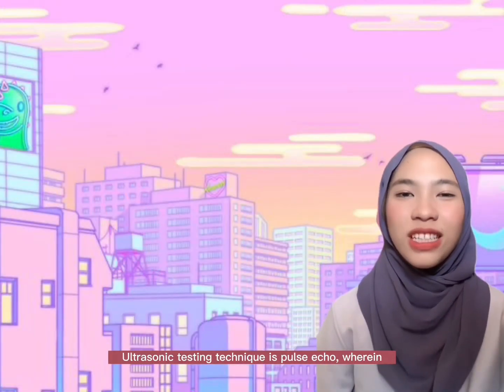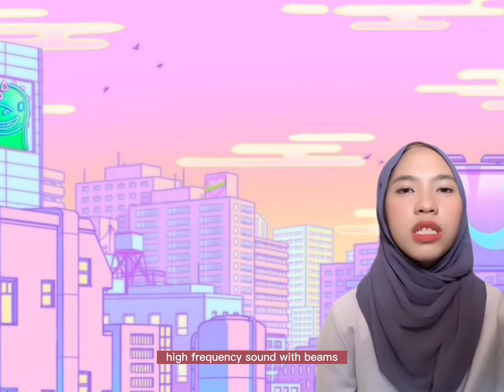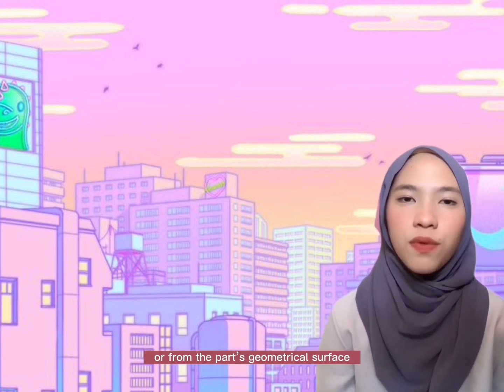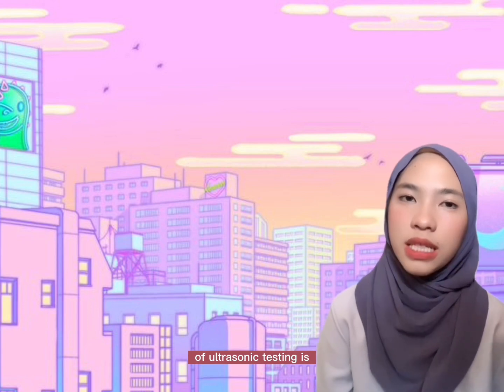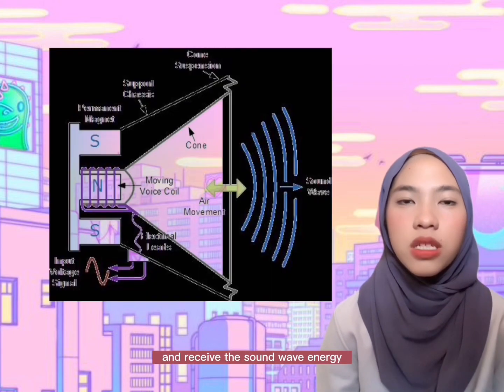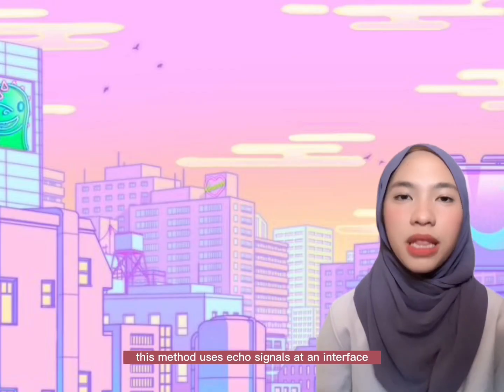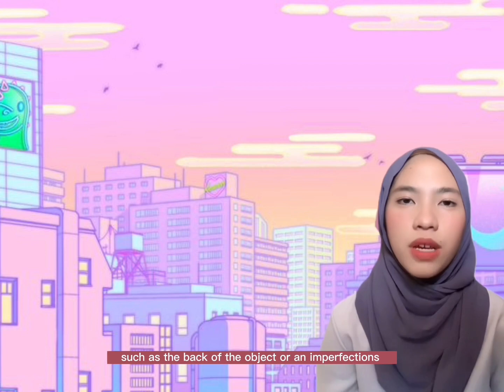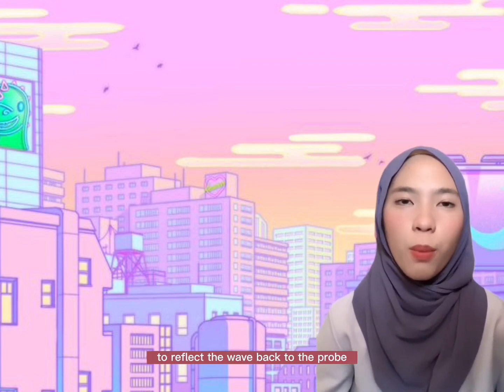The most commonly used ultrasonic testing technique is pulse echo, wherein high-frequency sound wave beams, normally ranging from 1 to 5 MHz, are introduced into a test object and reflections are returned to a receiver for internal information over the part's geometrical surface. The basic method of ultrasonic testing is transforming a voltage pulse to an ultrasonic pulse using the transducer. In pulse echo testing, the same transducer emits and receives the sound wave energy. This method uses echo signals at an interface, such as the back of the object or an imperfection, to reflect the wave back to the probe.